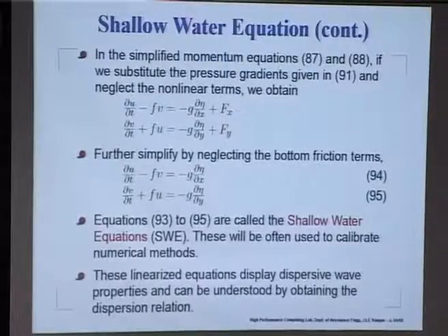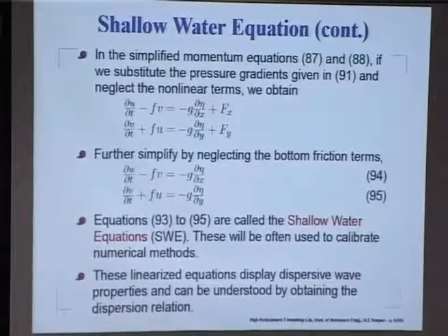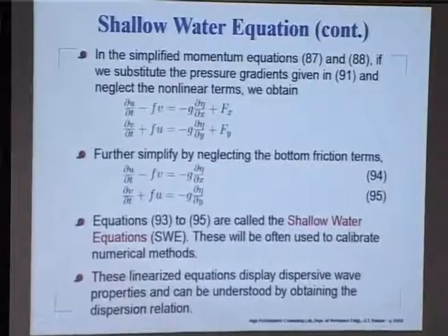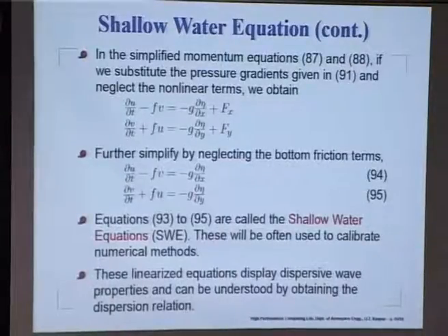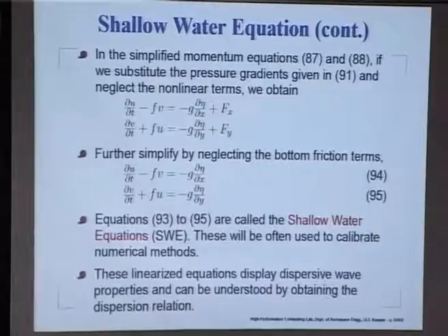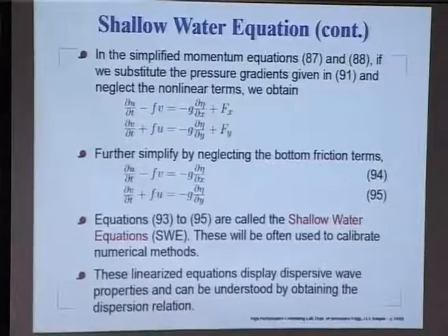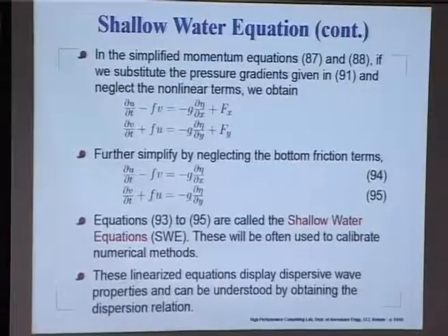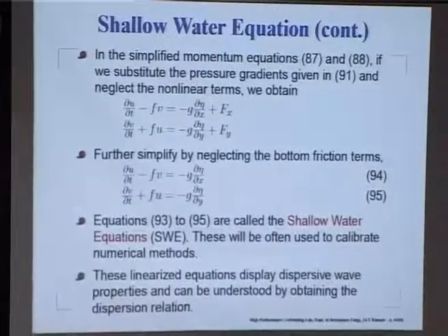Now, looking at the momentum equation, we have replaced del p del x and del p del y by these wave elevation terms, and these are of course our bottom friction terms. If we neglect those bottom friction terms, we get this, and what have we done here? In expanding the substantive derivative, we have also omitted those nonlinear terms, right. The nonlinear terms were there, like u del u del x, v del u del y, that have been omitted here, and the same thing about this.